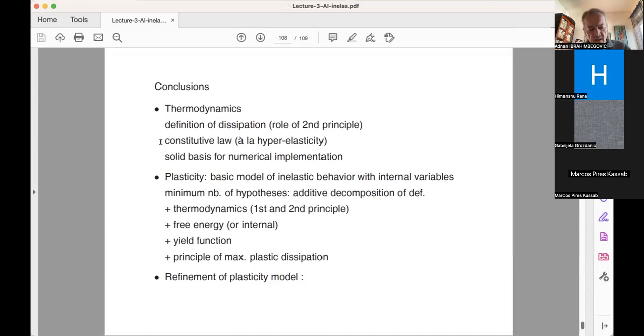In fact, you can even observe dissipation in many different ways. When you have plasticity, you take a paper clip that you put together these pages, and you start torturing it with cyclic loading. And if you keep your hand on this clip while you're doing it, you can feel that it starts getting warm. Typically, this dissipation is often really related to releasing the heat. For the quasi-brittle material, that's much less, and you can really not take it into account. But in any case, quantifying dissipation does require thermodynamics, which you've done to start with.